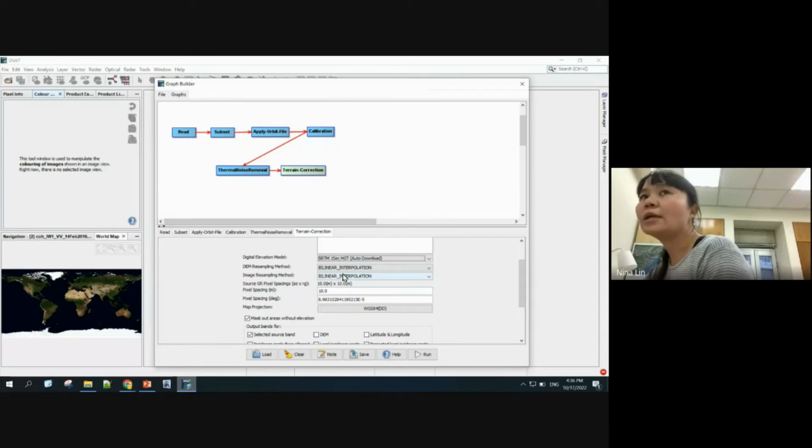So actually, people like to say that what is closer to the actual situation is that the resolution is closer to 15 meters, and in some cases, people may even say 20 meters. That's because it depends, as I mentioned, on whether you're closer to the satellite, something we call the near range, or farther from the satellite, in the far range. If the area you're interested in is farther, then your resolution is probably closer to 20 meters. So again, don't mistake this.